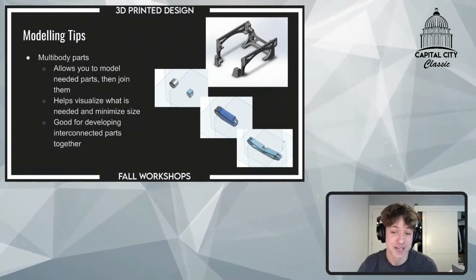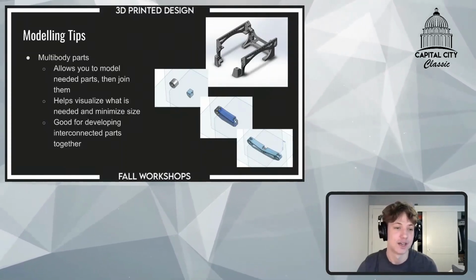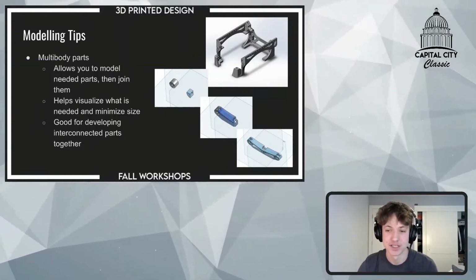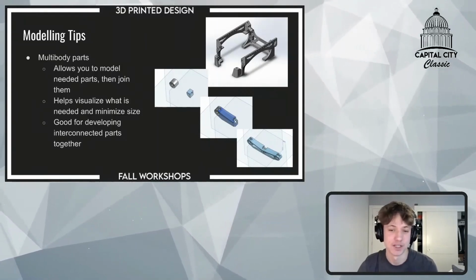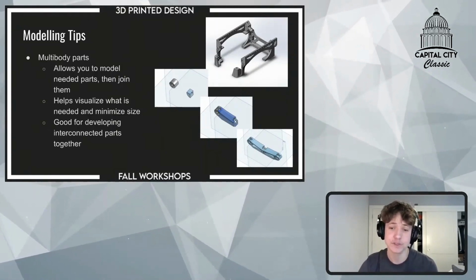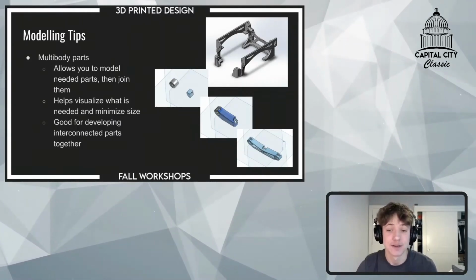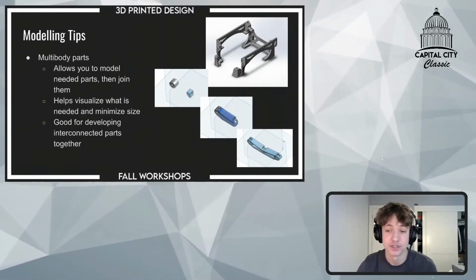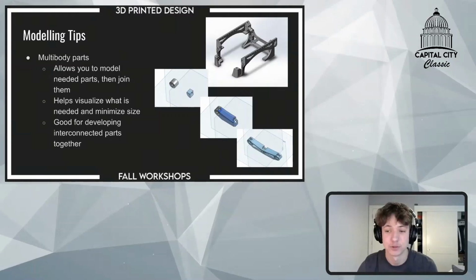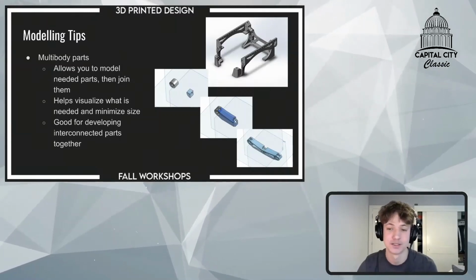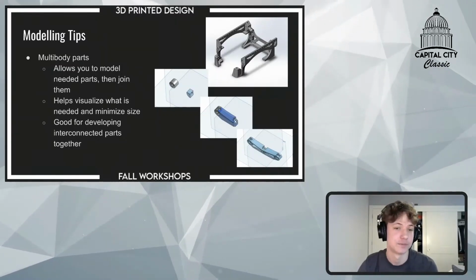The idea of top-down design simplifies this workflow. As I said, Onshape is kind of built around this idea, and SolidWorks has the capability, but it is quite limiting. This is great for making mounts for other parts or moving parts. You'll waste a lot less time going back and forth between part and assembly if you do this top-down design.